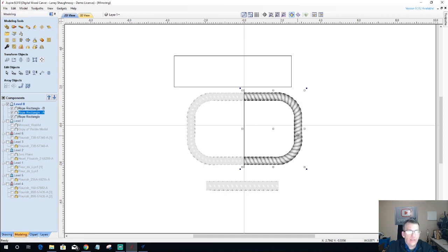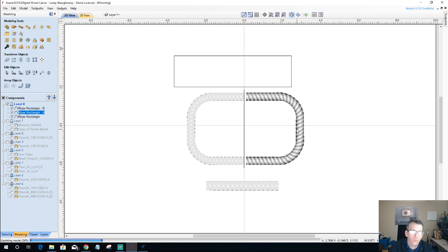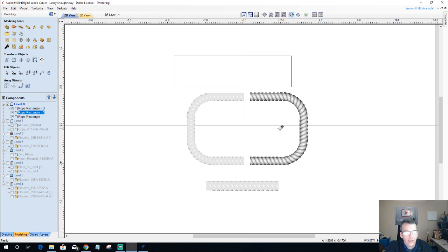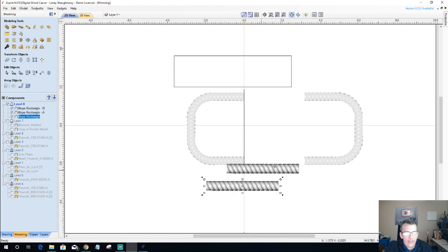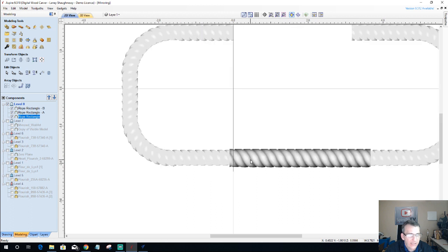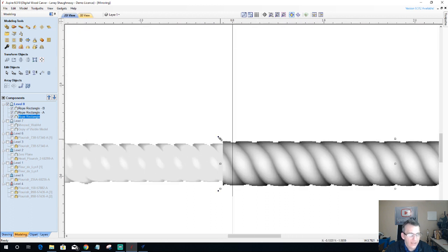Okay. So now I could come in, and I would want to split it to where my ends would actually blend and match, but that's what we have merge mode for. So I could take that and move that out. Split that model up here. The arrow keys are a little slow, so I'm going to hold my alternate key down to keep it on its plane, but I'm going to move it sideways there. And I could take and bring this up into place. Let me size this guy down. He's not the right size. Let me size him down.